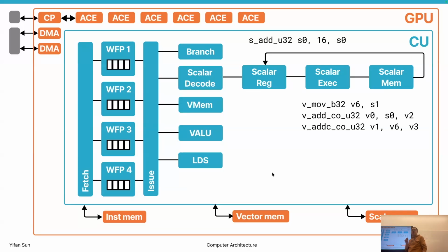There's no floating point calculating capability, so we cannot calculate decimal numbers. It's always integers, mainly designed for calculating addresses. So the vector memory can load the data, then it can be processed by VALUs. VALU contains floating point operations. That's basically the only unit that can calculate floating point operations.